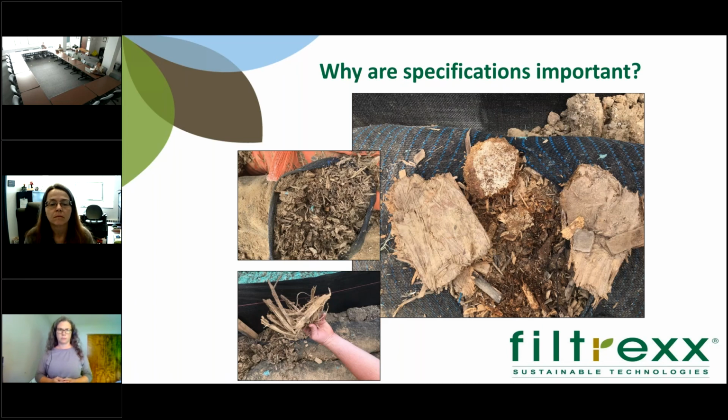The quality of fill that goes into these socks is also critical. You can see here, depending on where you get your sock from, for lack of a better word, you'll see a lot of junk blown into these things. It's not going to be clean, fine graded mulch. It's important that you have the proper gradation. A sock like this, where it's all loose, blown in, smaller fines, is not going to do much in terms of filtering out the dirt and the soil so you can have your clean water coming through.